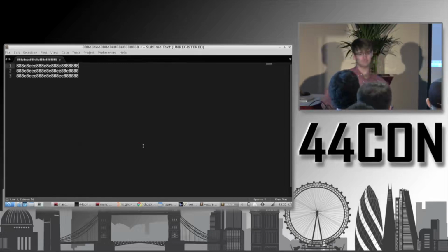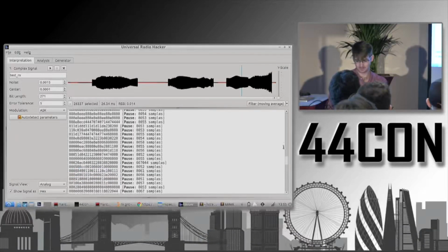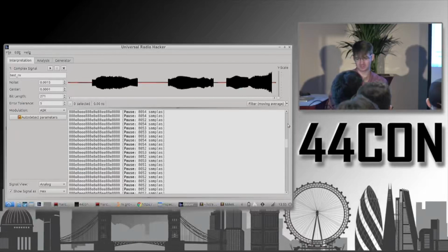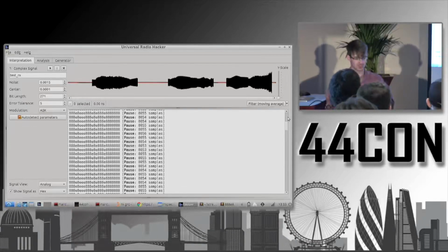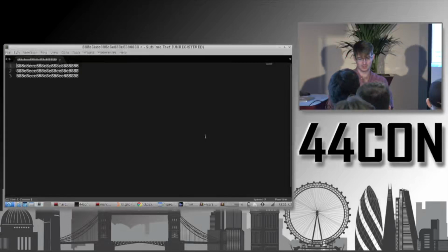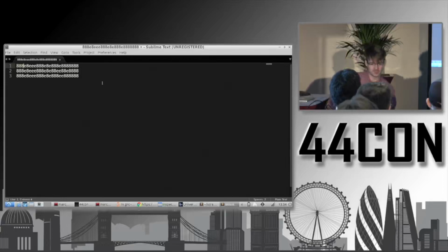Cool. Okay, so basically what I did is I scrolled through URH and found packets that look representative of data coming from each of the 3 pager systems that you set off, because you set off 3 different pagers in that capture we generated. Now we can take a look here and visually see the fields that are changing based on the address that he sets off. We've got our preamble that we're expecting to look for. It looks like we have some kind of header that follows it.